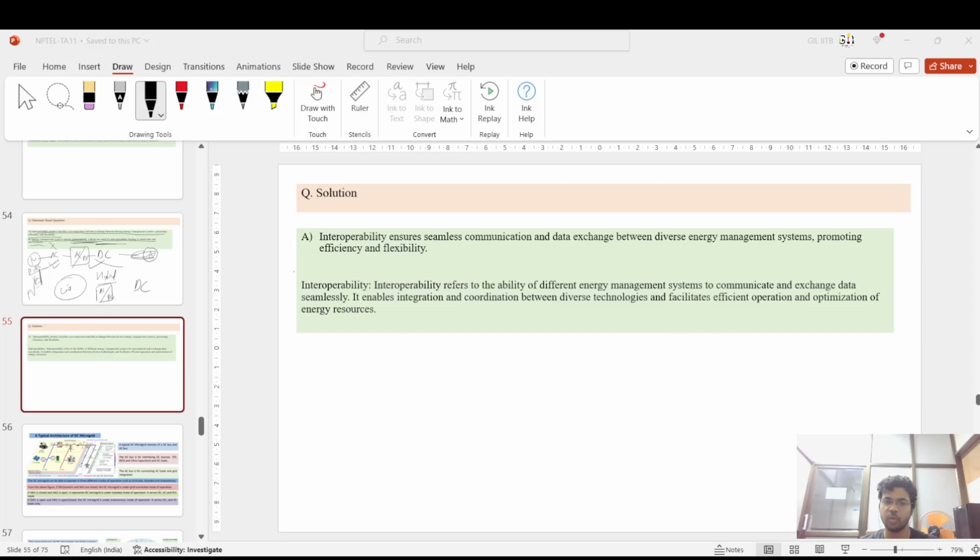Actually, there are schedules, because day-ahead scheduling should be done for which generator, and how much power is to be taken by the SLDC from these distribution sources. If the plant is there, SLDC has a certain contract with them that at this point in time they need this amount of power, on a day-ahead schedule basis. So they have to supply this power at that moment. But if they fail to supply, then penalty slabs are there.